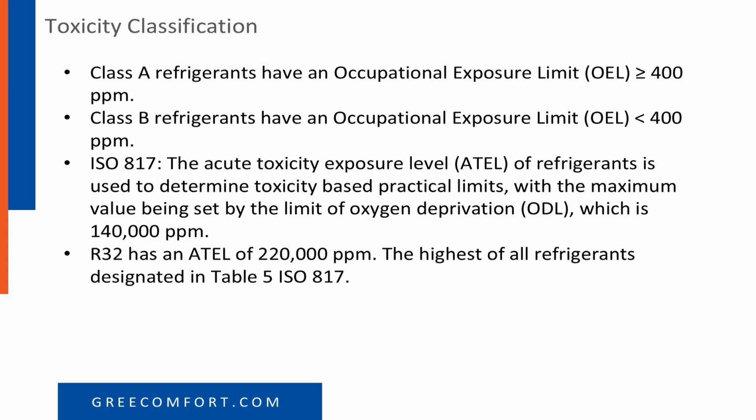Further, you can talk about ISO 817, which covers the acute toxicity exposure level, or ATEL, of a refrigerant, which is used to determine the toxicity based on a practical limit. The maximum value of that is set by what they call the oxygen deprivation limit, or ODL, and that's set at 140,000 parts per million. That means at 140,000 parts per million, there's so much refrigerant in the air, you're going to start to asphyxiate. There's not enough oxygen for you.